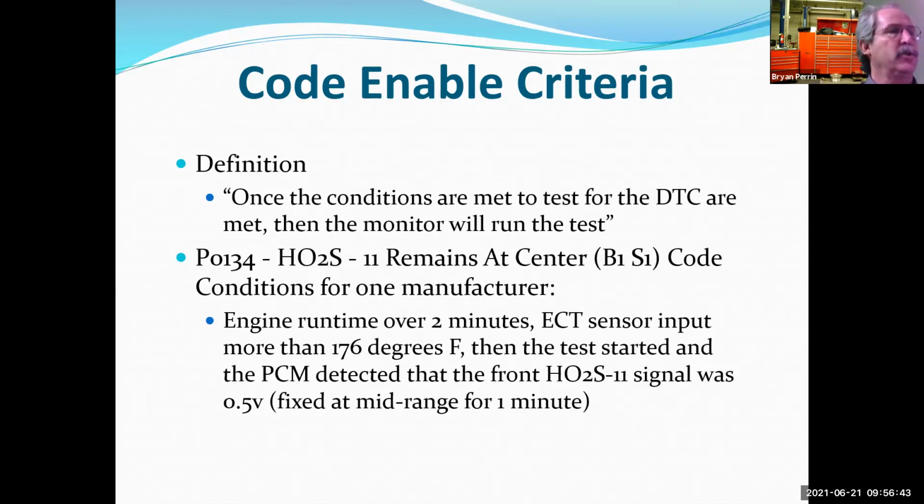It saw the sensor, with the engine warm after being run for 2 minutes, see the oxygen sensor not move for more than a minute. And it was not moving, stuck at 0.5 volt or close to it. That's what it saw. So before I go test the oxygen sensor, before I go look at the scan tool data, I want to do this first, because otherwise I'm just looking at data going, gee, it looks okay, or it does look okay. I really don't know, because I don't know what is making the computer unhappy.